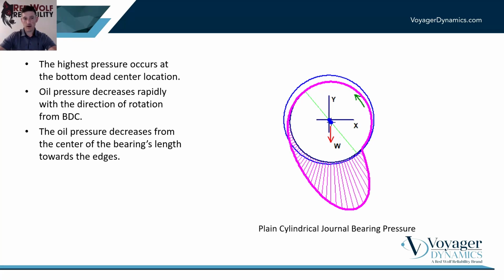Now, you'll notice if you watch closely, the area that supports that shaft increases further as we speed up, but the magnitude actually increases a little bit as we get close to that 3600 RPM. That's because we have a certain amount of unbalance on this rotor, and so unbalance changes with speed and increases with speed, so our load actually is changing a little bit throughout the whole simulation.